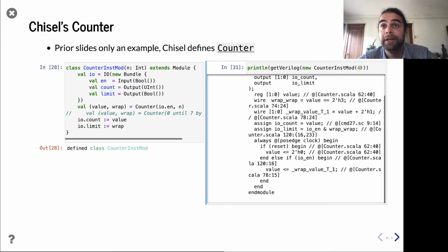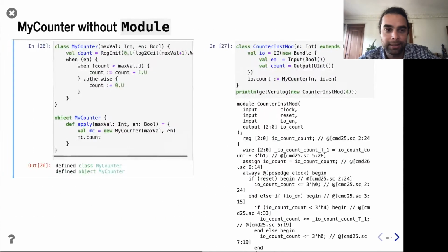It's actually the number of things you want. So if I ask for a Chisel counter with 4, you're saying I want to count 4 things. Under the hood, it's going to count 0, 1, 2, 3. But the maximum value is actually that number minus 1, right? Versus our counters, we've been kind of giving the maximum values.